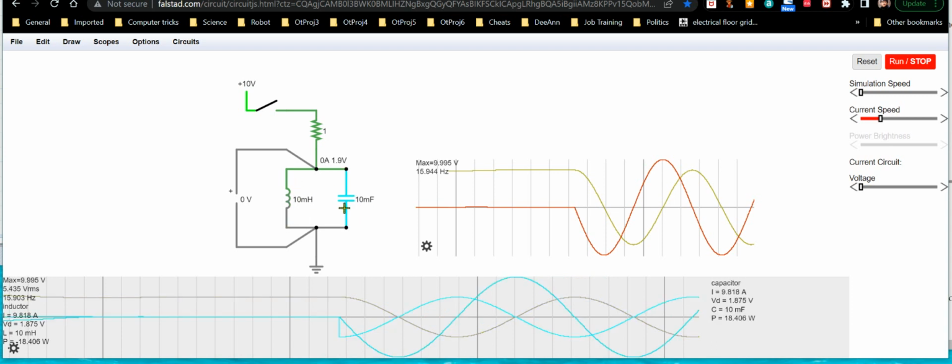If not, what you're going to see is these things have 2 different voltages across each other, despite the fact they're in parallel. So you'll see 2 voltage waveforms, one for the capacitor and one for the inductor, that's 180 degrees out of phase. But that's not true. It's the current waveform that's 180 degrees out of phase, but the voltage waveform is identical because they're connected in parallel.